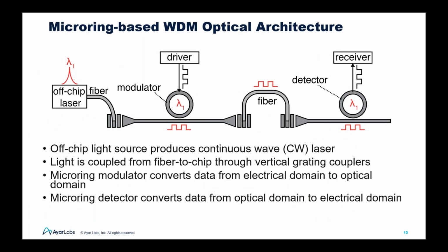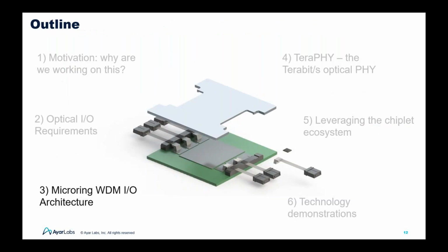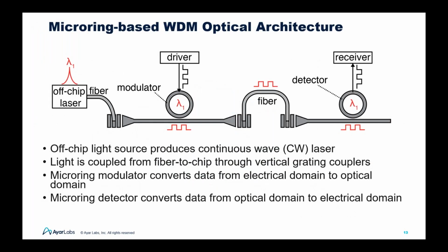One of the challenges for the optics is that usually the optical modules take so much area. That's why it's pretty hard to make them integrated with the CMOS. Mainly because the optical modules are using something called a Mach-Zehnder modulator, but there is another solution that we call a micro ring, and that micro ring is pretty small. It's in the few tens of micrometers. Then we can integrate it in the CMOS fashion also. That was basically the motivation and the solution that we picked.